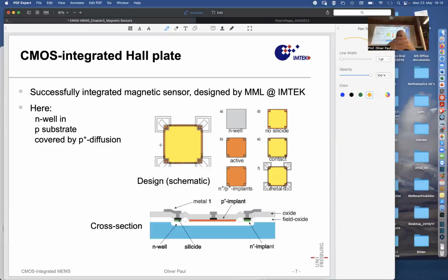What you need is a conducting region that has this shape of some block, with a thickness and then a length and a width. How do you do that? You make an N well here, an N well in a P substrate, P silicon, yellow on blue. It's not ideal, I could switch back to black. P silicon substrate, and then there is an N well implanted in there.